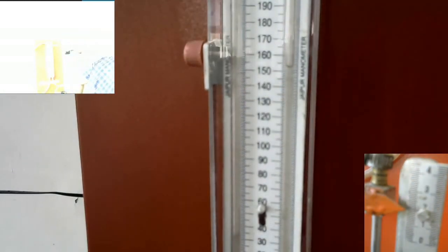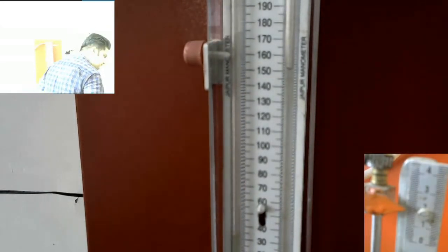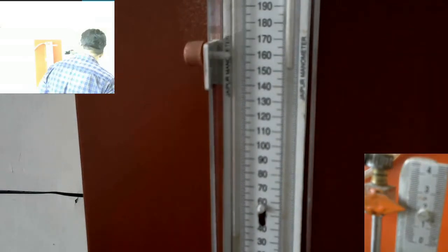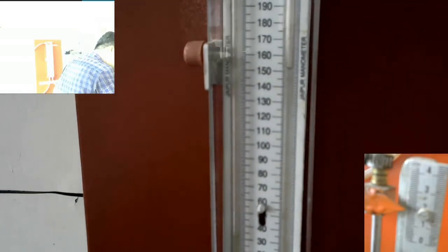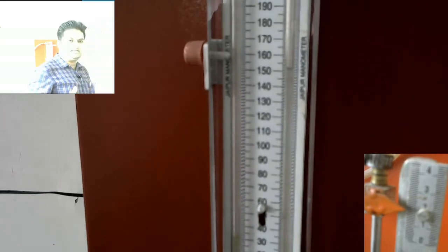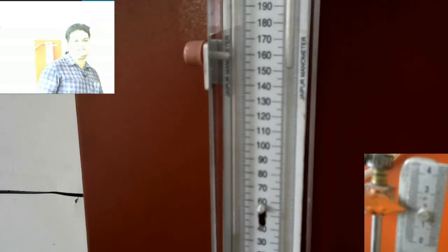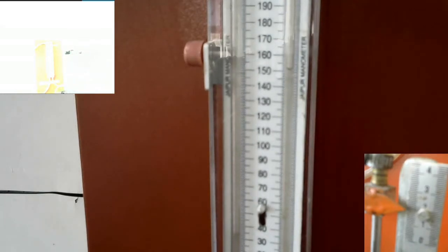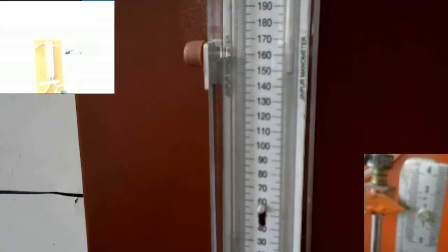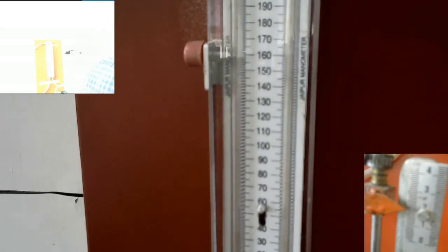All right, 155. You can see that you can take the lower meniscus, not even 155, 154. Surprisingly, the upper measuring tank has not changed much, but the lower one has. Again I take the reading for the time required for a 10 centimeter rise. So again I close the outlet of the tank, and I am ready to take my readings. All right, so I'm done. This time I got 8 seconds. Again, the same reading for time.